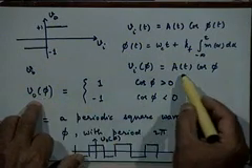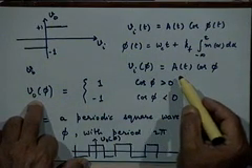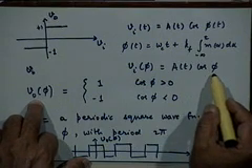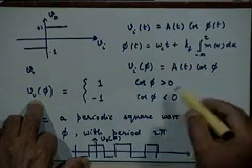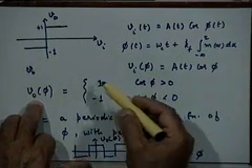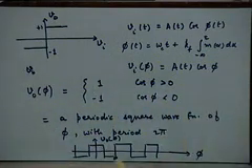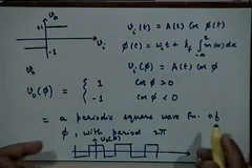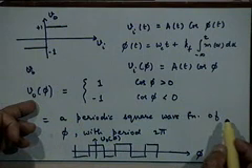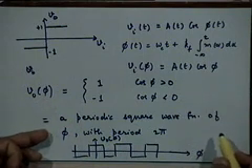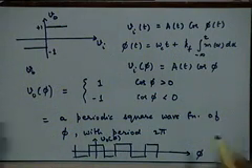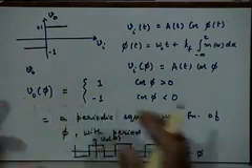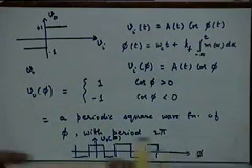V naught of phi will not have any dependence on A of t, right, it will have a dependence only on cos phi. When cos phi is greater than 0, it is plus 1, A of t just disappears from the picture from our consideration, it is absolutely of no consequence. So, this is the important point, that this thing as a function of phi is a square wave function with a period of 2 pi, and therefore, I can represent this function in terms of a Fourier series, not as a function of time, as a function of the phase phi, okay.